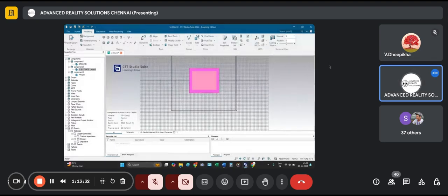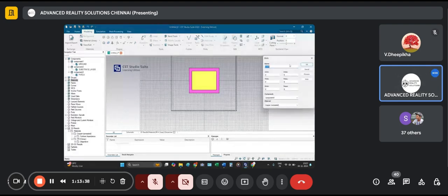Closed it by mistake. I will include it. Go to brick. This is the feed. X min is minus 0.9 by 2 from the calculated value, 0.9 by 2. Y minimum is 0. Y max is 18 by 2. I think I have mentioned it clearly.